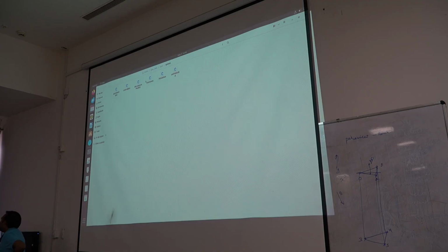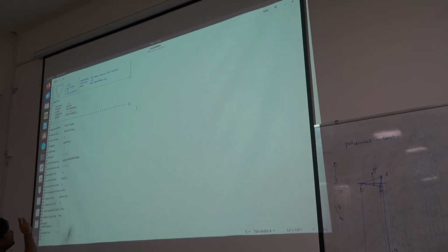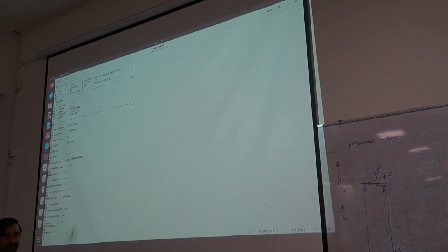Okay, so now I will be going to controlDict. In controlDict, I have to tell from where to start. So I have written startFrom latestTime. What does it mean? Earlier it was startFrom startTime, but now it is written latestTime.